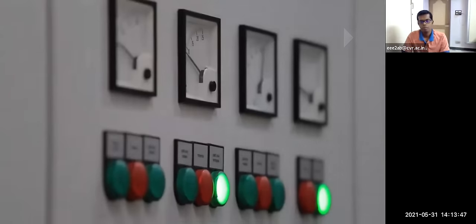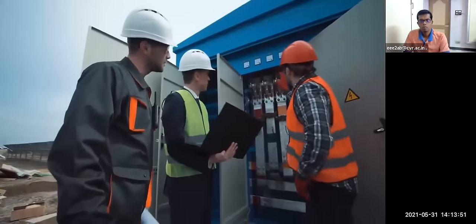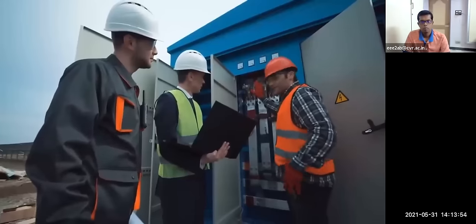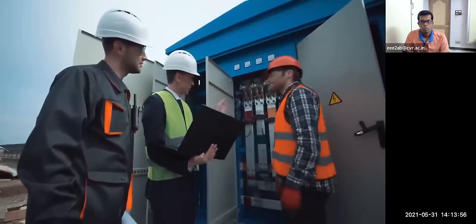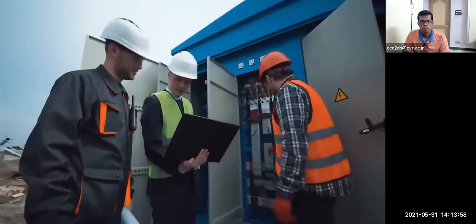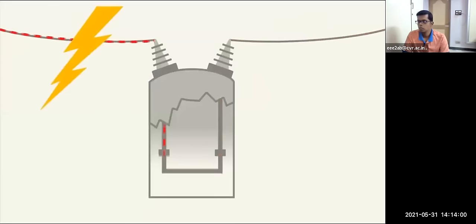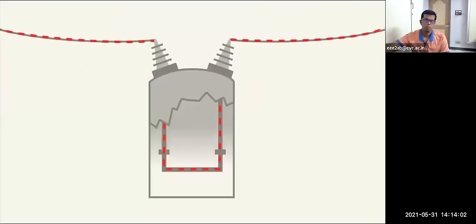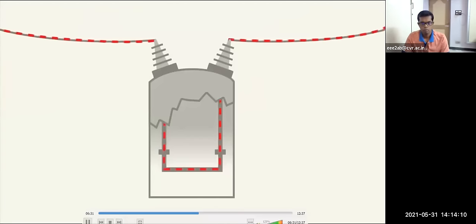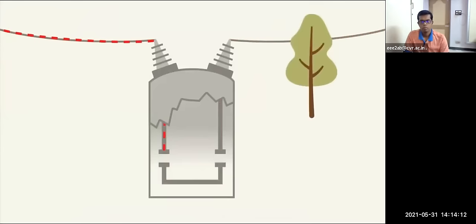There's more control about how and when current gets interrupted. Not every fault is the same, and sometimes operators even know about a disturbance ahead of time and can trigger breakers early to prevent cascading failures. Many faults are temporary, like lightning strikes or swaying tree branches. A special kind of circuit breaker called a recloser can interrupt current for a short period of time and re-energize the line to test if the fault has cleared. Reclosers usually trip and reclose a few times depending on their programming before deciding that a fault is permanent and